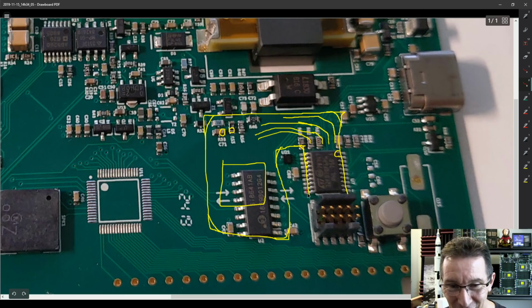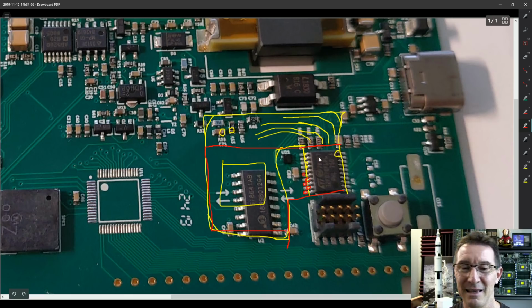Whether or not I go for little holes here like this, or little vias like that, staggered vias, and just have the board shaped like that. I think that'll probably do the business. Yeah, I'll just run with that, because then we can remove that capacitor, and we can either put it on top of the flex, or we can do some muntzing and physically take out the capacitor, because it's not a big deal. It's just a bypass cap, and you can put it on the flex if you want. I could put a pad down for it, but yeah, it'll work.